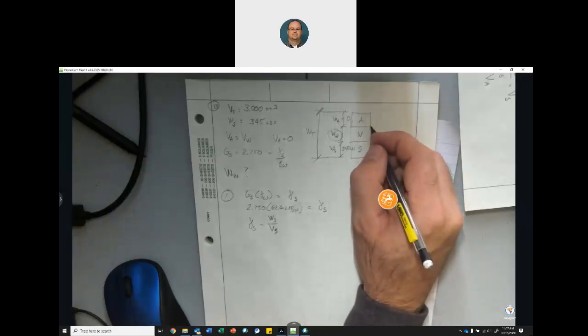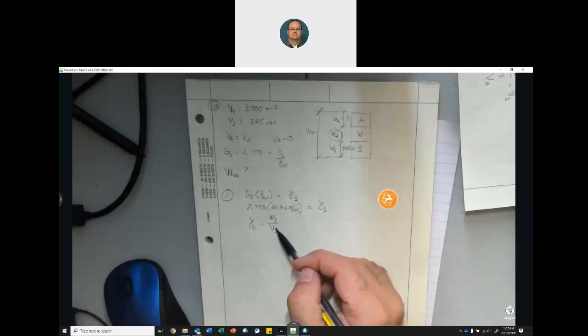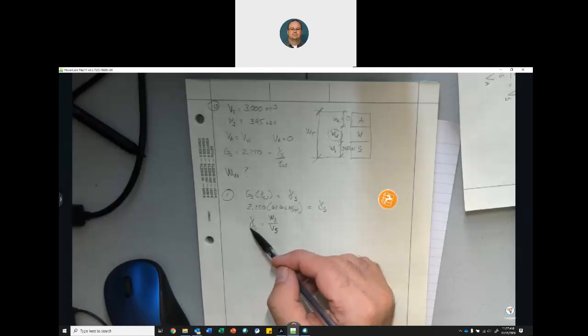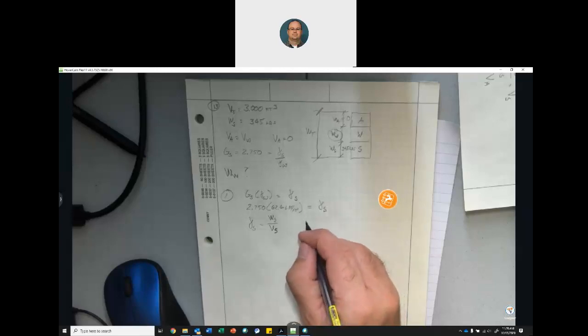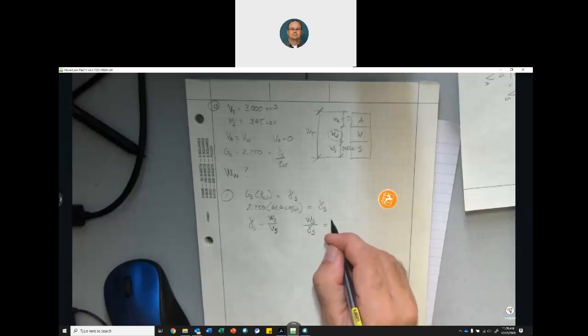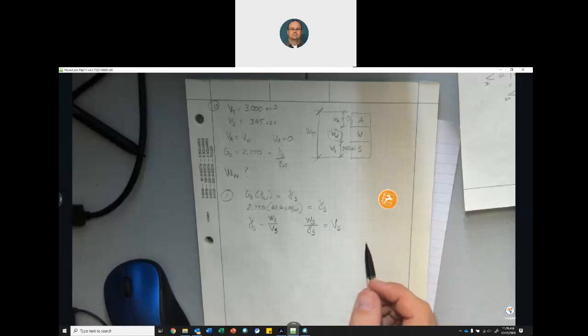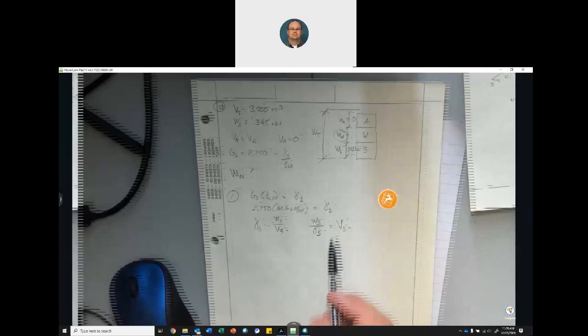So I have weight of solids, I can find my volume of solids. Let's take, we know weight of solids, and divided by my unit weight of solids, now gives me my volume of solids. Okay? So this to this to this.